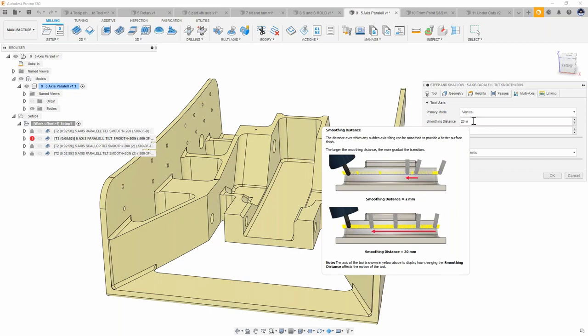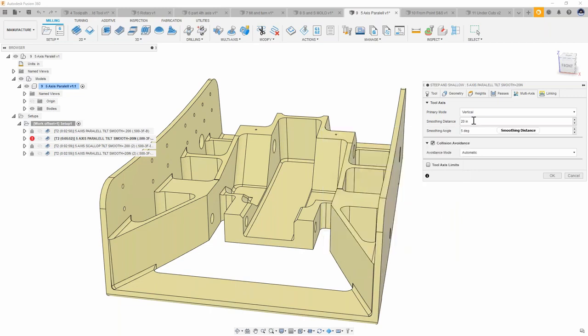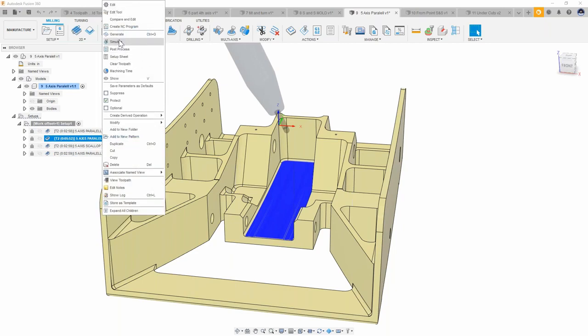Before it was set to 200 thousandths, and what that does is when that tool was stood up and it was traveling down that path, when it saw a collision, it said I have 200 thousandths of room to fix this. So that's why that jerk motion happens in such a short amount of time, because it has to correct it in that amount of time. So me giving it a bigger distance here, 20 inches, let's see how that looks.